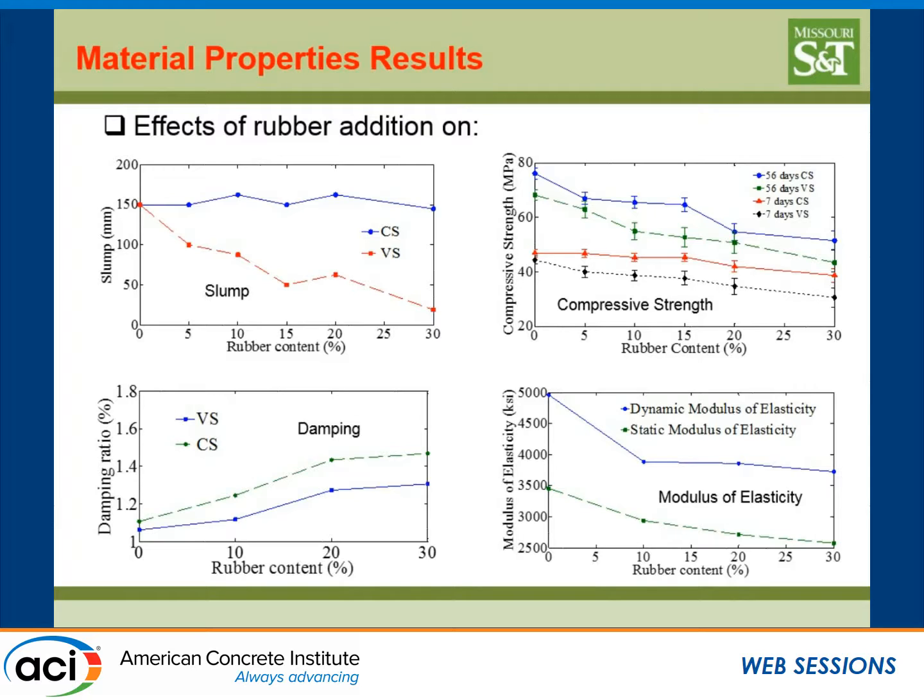And here we just present one graph. We have actually published one full paper about the damping characteristics of these two materials. The way that we measure damping, using too many approaches, falling mass, we use also a hammer impact, we use some non-destructive testing, so we use a lot of things to measure the damping. But this is kind of our conclusion here. And again, this is a very low damping because we measure for the elastic range and at the material level.